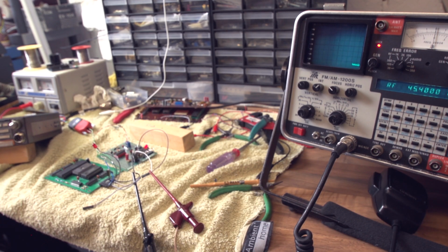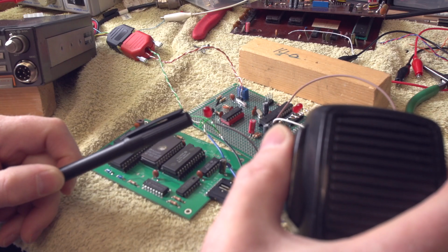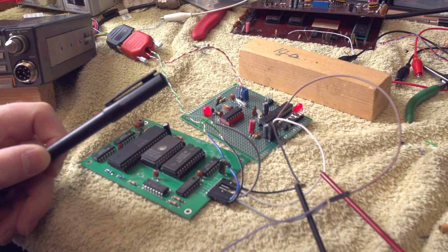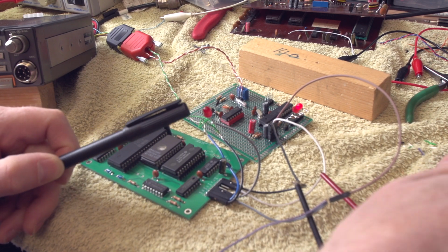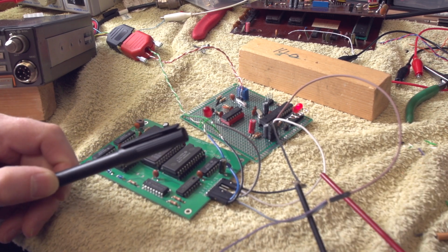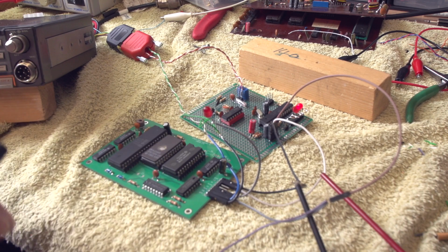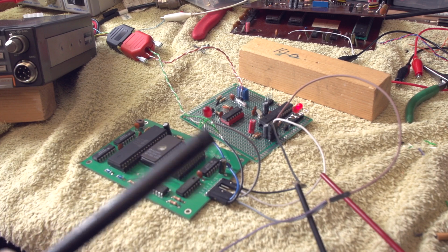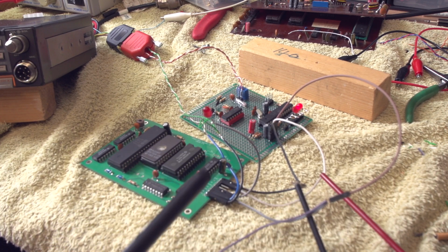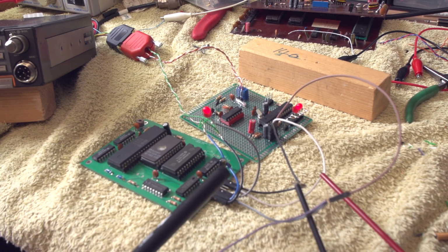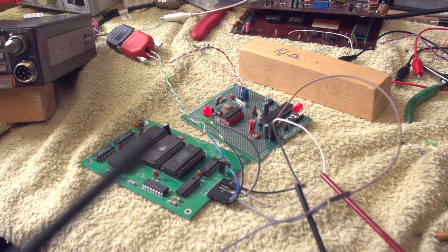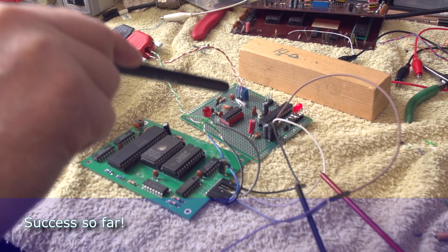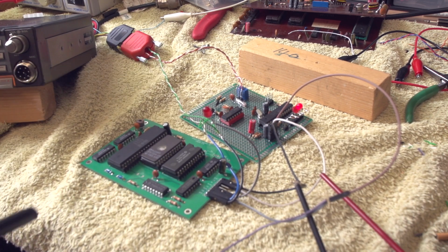Okay, I'll just zoom in on that a bit. There you are. 1, 2, 3, 4, 5. Just talking at the microphone, makes no difference. Now this isn't on the air, it's not actually transmitting or anything, but you can see that the card has activated and it's sending its CW ident. And that's because it got both the squelch or busy line activated, and it got the CTCSS signal from the decoder as well. So that's looking really good so far.